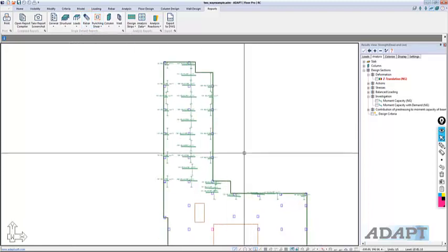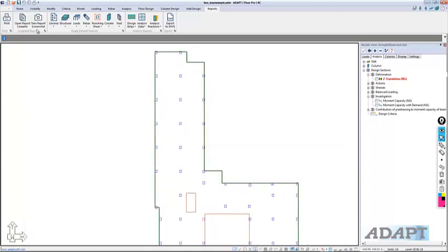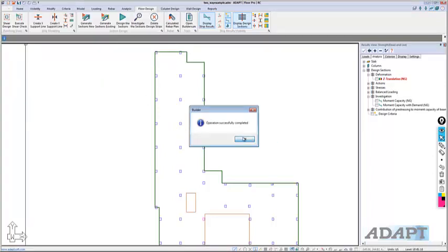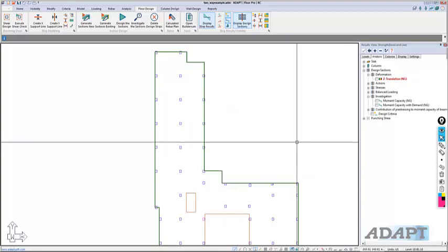So the punching shear check after you analyze, let me go back to the default display. We can go back to floor design. This can actually happen once you analyze. You can execute the punching shear, and the program will graphically show results for punching shear. Now, this result display settings is upcoming this month in the program.